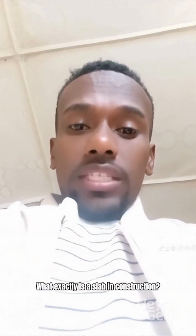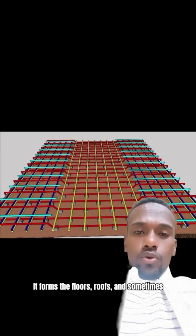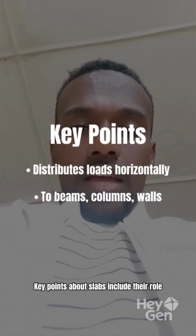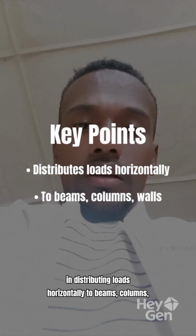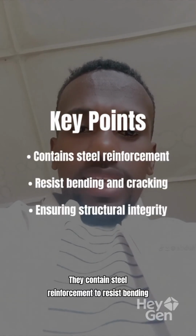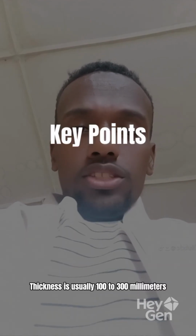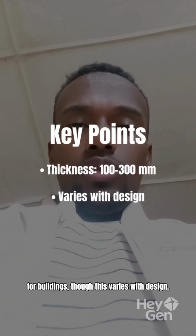What exactly is a slab in construction? A slab is a flat, horizontal structural element made mostly of reinforced concrete. It forms the floors, roofs, and sometimes ground surfaces of a building. Key points about slabs include their role in distributing loads horizontally to beams, columns, or walls. They contain steel reinforcement to resist bending and cracking, ensuring structural integrity. Thickness is usually 100 to 300 millimeters for buildings, though this varies with design.